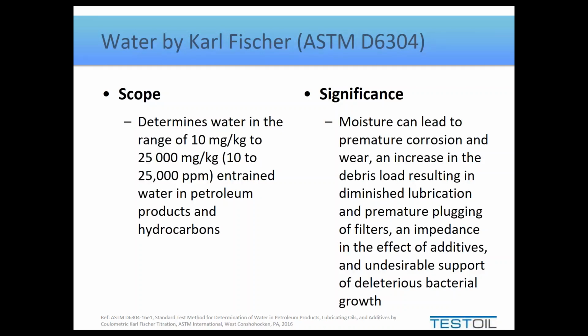And in the metalworking industry, we even have some water and oil emulsions that range from 5% water to 95% water. So Karl-Fischer is typically used on all those, even though by its scope, it's meant to measure water more in the lower concentrations.